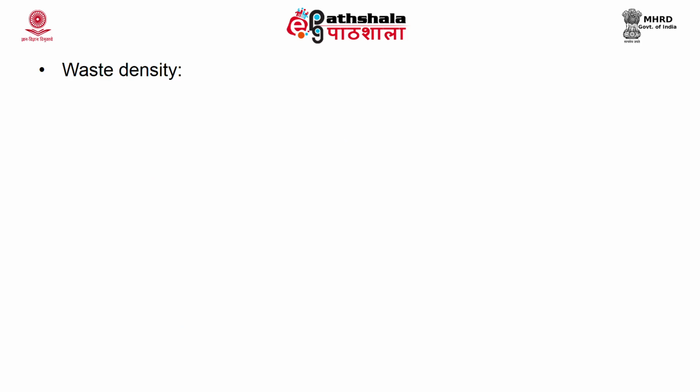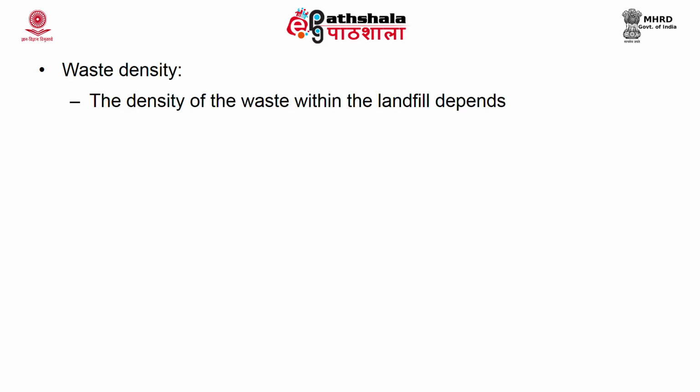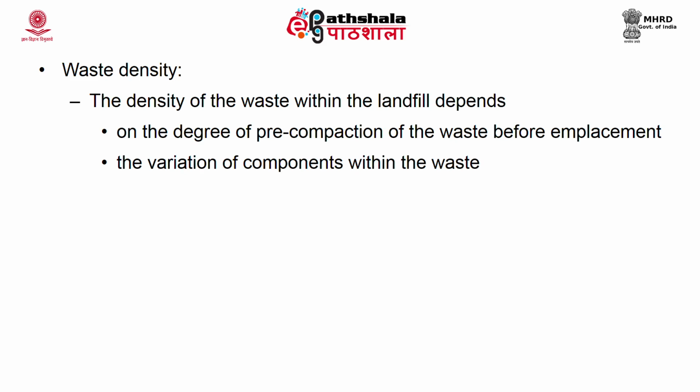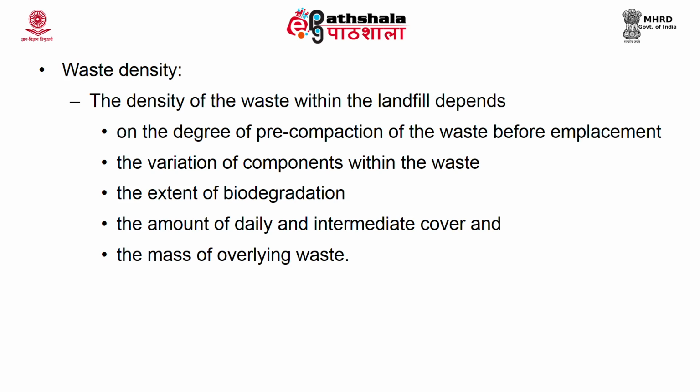The next one is waste density. The density of the waste within the landfill will vary depending on the degree of pre-compaction of the waste before emplacement, variation in the components within the waste, progression of degradation, amount of daily and intermediate cover and mass of overlying waste. Because the overlying waste, obviously it will be heavy. So, it will press the waste which is lying below.